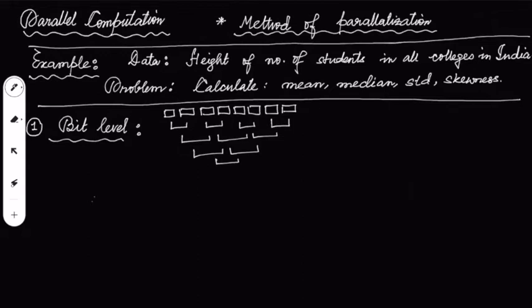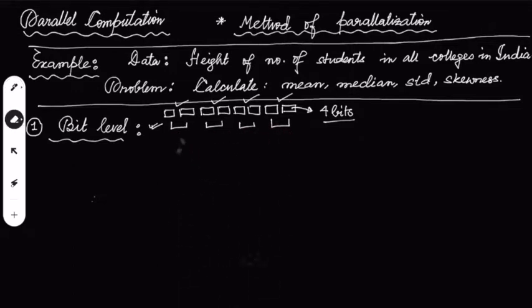Now, if I look at a computer, each of these numbers may be represented with 4 bits. Okay. Each of these numbers are represented with 4 bits. So in the first round of operations, we are adding 4 bits with 4 bits here, then 4 bits with 4 bits here, and doing that 4 times. So there is some mistake here. I have to add these two, and then add these two. It's only 3 rounds that we got. Anyway, so I'm adding these 4 bits with the other 4 bits. But how this adding is done, there is something called an adder in a computer, so that has to be a 4-bit adder to add 4 bits with 4 bits. And this adder is essentially just XOR gates, 4 XOR gates essentially.